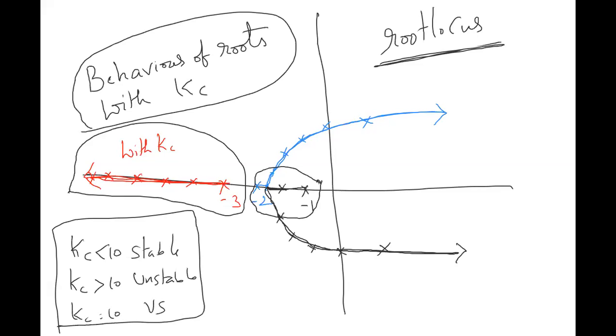Maybe something will happen in a second. So that is why there is a concept called tuning of the controllers when you start the plant. What you do is you start with a band of 100%, 1 by tau I equal to some value, let's say 1, and tau D equal to 0. Don't use the differential in the controllers. Slowly put 100%. Then what do you see?